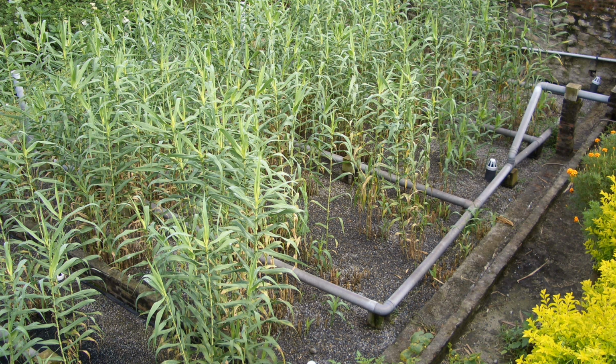The benefit of vertical flow is better aerobic conditions, improving performance. Generally, a surface area of about 1 to 3 square meters per inhabitant is required. As in the case of horizontal wetlands, vertical wetlands also require the influent to be well settled in a primary treatment stage before flowing into the wetland.